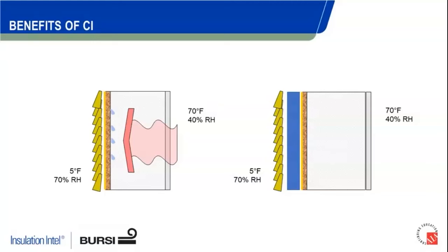Now, if that's under those conditions for an extended period of time, and you're not able to dry out or warm that wall back up to help alleviate those condensation risks, you can get, of course, significant buildup to the tune of actually having detrimental effects on that system. Of course, this is an exaggerated example, as you see here, but diffusion is a fairly slow process, and we don't have any specific numbers tied to that condensation risk, but if you're under a steady drive for 30 days or more, you can start having significant condensation buildup in a wall system.